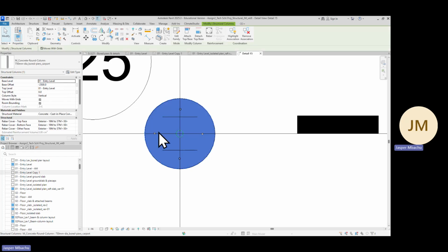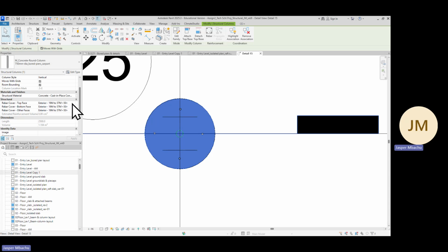Yeah, please, when you select them, come to the rebar cover, because at times it doesn't select automatically, and choose the 50, just write 50. When you pull it down here, you select the one that has 50 there, and also the other one too, all faces 50.